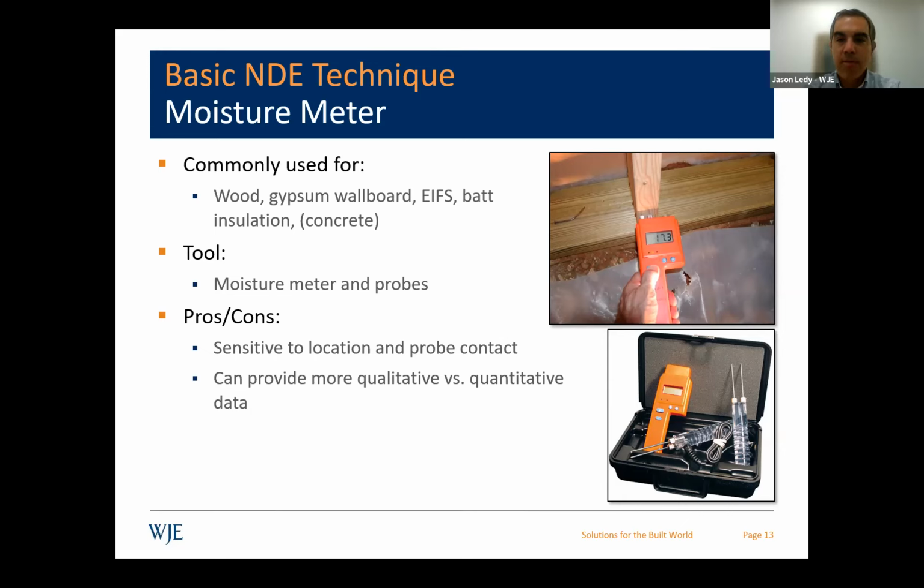So that you could get a wide range of results. One of the drawbacks is that, depending on how you insert the probes and how they contact, you could get a variation in results. If you were really looking to confirm the moisture content, you would want to get a sample and then have the moisture content of that sample tested to verify.